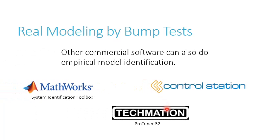You don't have to have gigantic, huge, expensive distributed control systems in order to do this type of analysis. There are smaller software packages that can do it for you. You can do it in MATLAB. There's a special tool, the System Identification Toolbox. You can do time domain and frequency domain data, and it can analyze and kind of guess what type of model. You can propose that it might be a fourth order model. I don't know how you would decide that, and I've talked to control PhDs, and they also say you don't really have a way of knowing whether it's second order or fifth order.